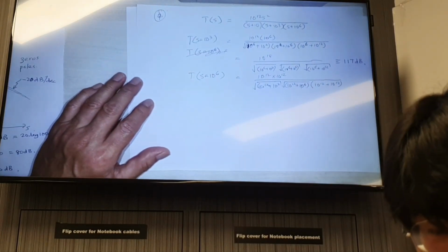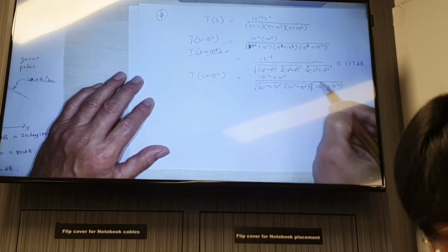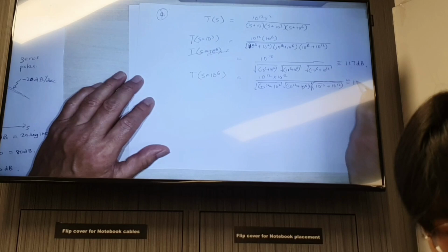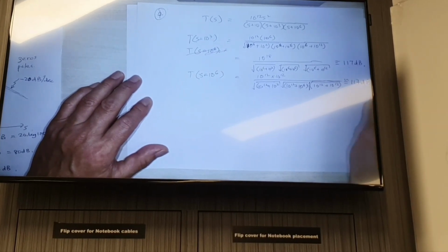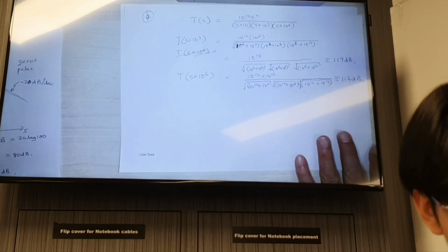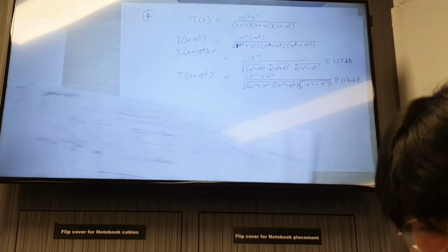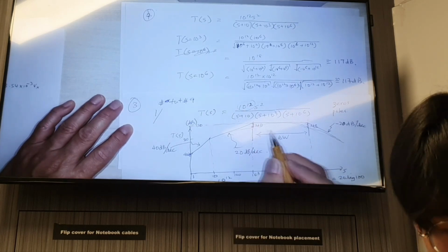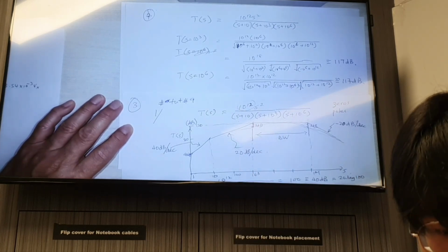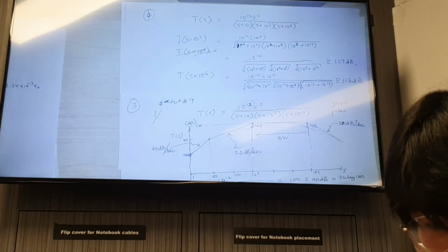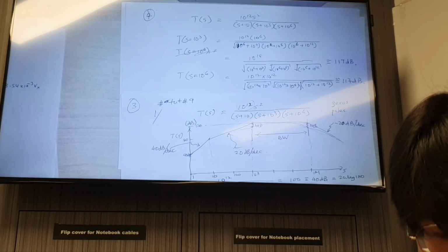If you evaluate this in dB, you find that it is again 117 dB. So that's why on both sides you have 3 dB below, and that's why this is known as your bandwidth. So the bandwidth is always 3 dB below the maximum value, the starting and the ending point of the bandwidth.